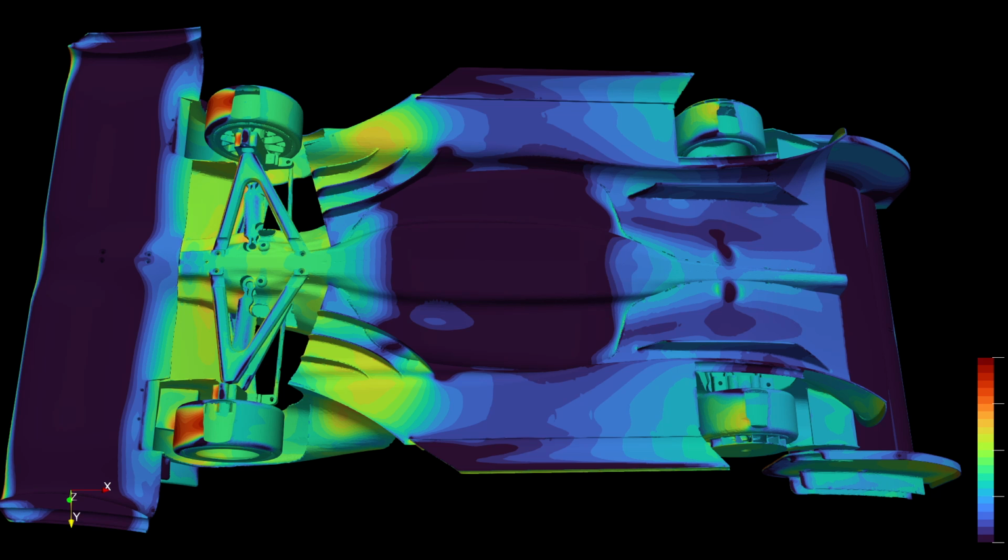Because I wanted to maximize the downforce and limit the aerosensitivity of the floor, we have two long and very deep venturi tunnels that take the air in here at the inlet and compress it along its length until it reaches the throat of the diffuser, which is the narrowest bit of the diffuser, and then expands the air as quickly as possible through the outlet. This creates a low pressure zone at the throat of the diffuser where the air velocity peaks. Now, this particular diffuser looks a little bit different than that, and I'll go into why that is.